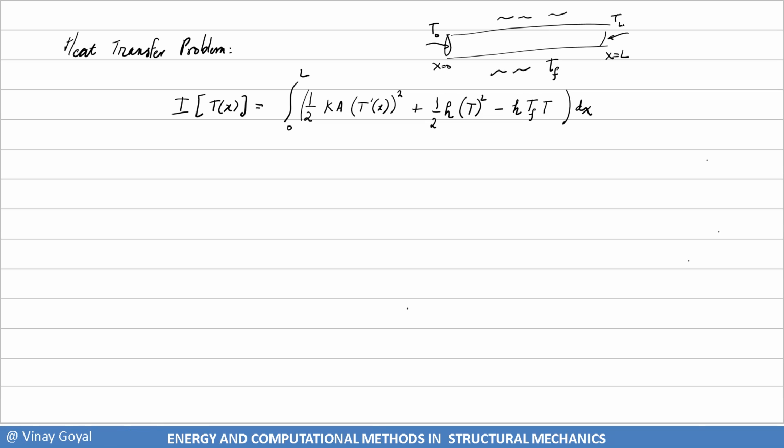You can verify very quickly that the essential boundary conditions for this problem are anything specified on T. And so I need to somehow satisfy that. So why don't we come up with an approximation theory for that? We will use Rayleigh Ritz. We cannot use a constant value because the derivative of a constant gives you zero. Zero squared is not very useful. So at a bare minimum, it needs to be linear. Linear may not do that great, so we could use quadratic. But that's beside the point.